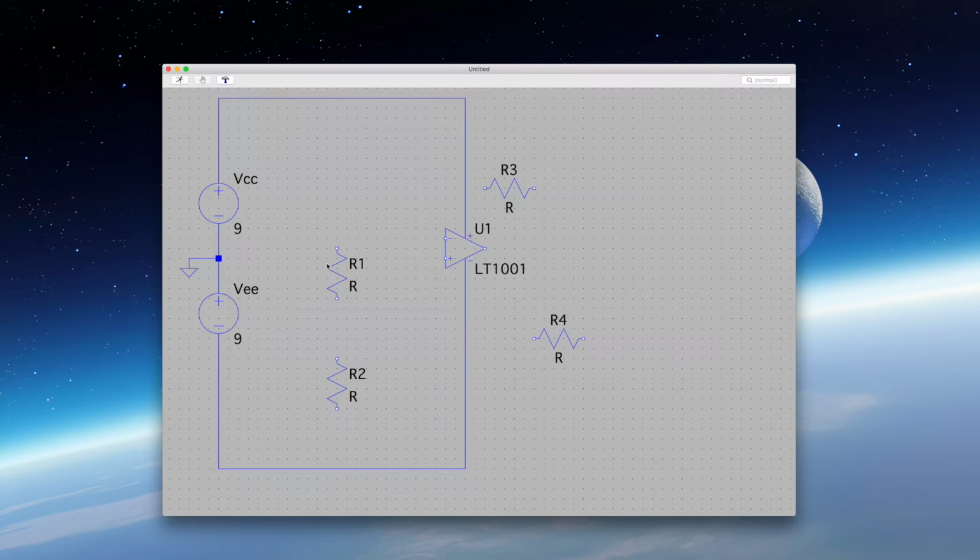All right, so let's go ahead and draw some lines. This would go from here to the negative input of the op-amp. We're going to go from here and cross over without touching the other wire right there. We're going to create a forward wire where we will sample our V out from.